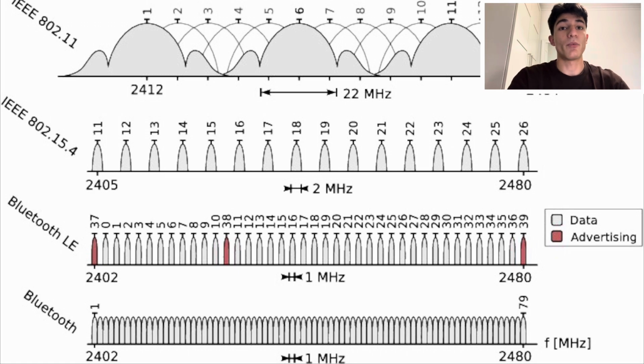Both Wi-Fi and Zigbee operate mostly in the 2.4 GHz industrial, scientific, and medical, or ISM, band, a free-to-use part of the radio spectrum, and that causes them to overlap or interfere with each other. Here's the thing, Wi-Fi signals are much stronger. They transmit at higher power and over a wider bandwidth. Zigbee signals are weaker and narrower but can be overwhelmed if a Wi-Fi device is nearby on overlapping channels. When Wi-Fi and Zigbee signals overlap, Zigbee packets might get lost or delayed, causing smart home devices to respond slowly or disconnect. It's like being in a crowded room where Wi-Fi is shouting and Zigbee is whispering.